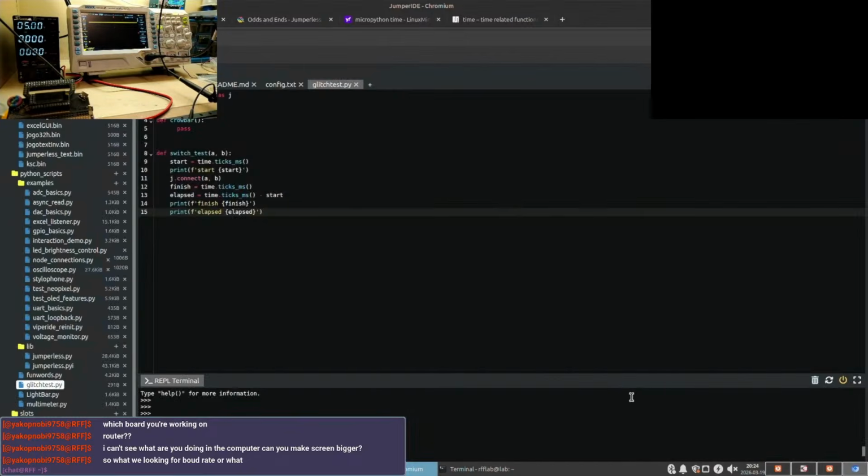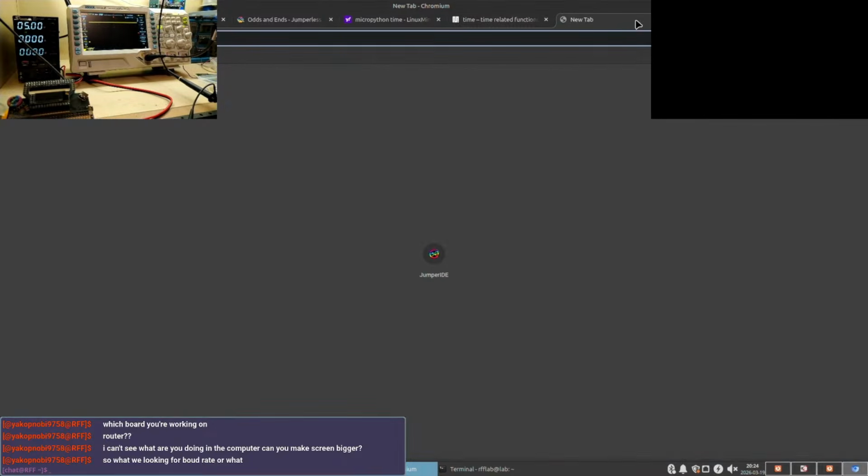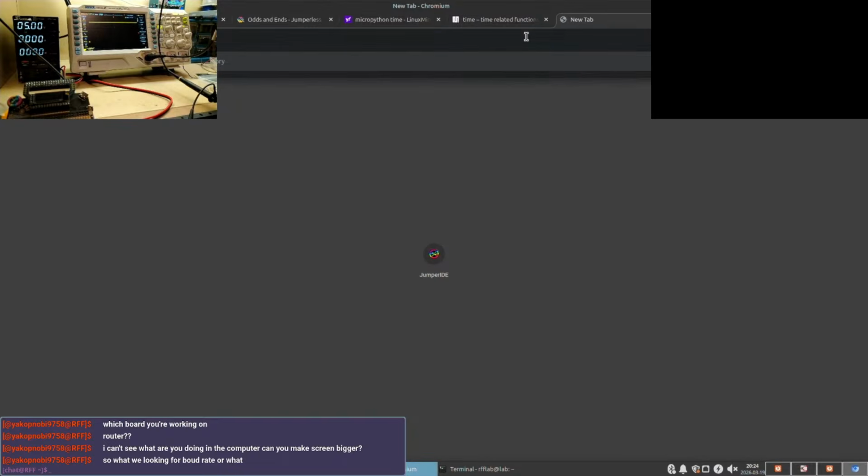Okay, so that's problematic because it ended up powering the board externally, which you're not supposed to do. So it got a little hot, which is not a big deal. It didn't burn itself out. Apparently, these things are pretty durable. So, what do I want to do now? How do I power this thing without burning up the jumperless? I guess I need like a shunt resistor, right?